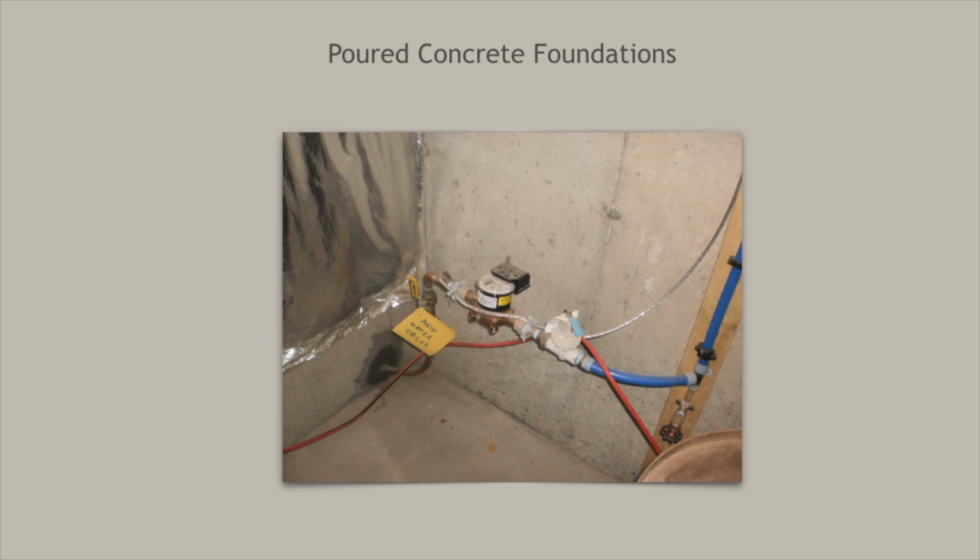If an outside foundation crack is left for extended periods of time without being repaired prior to backfill, water that gets trapped inside the crack will freeze and expand, thereby increasing the size of the crack and allowing more water to penetrate it, and the cycle will repeat. Therefore, over time the process will repeat, eventually causing a structural failure.